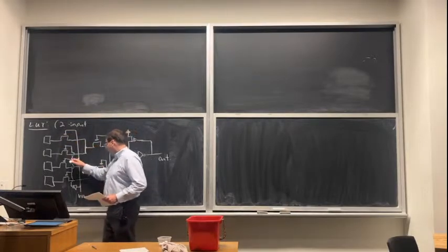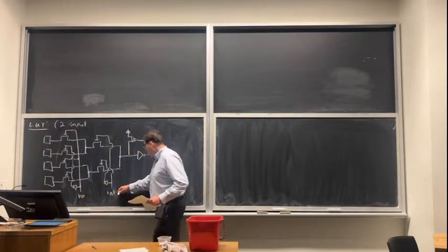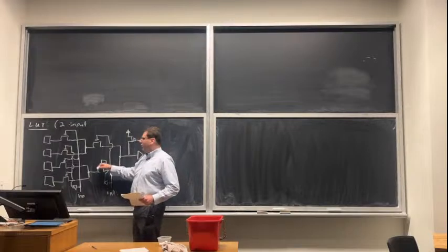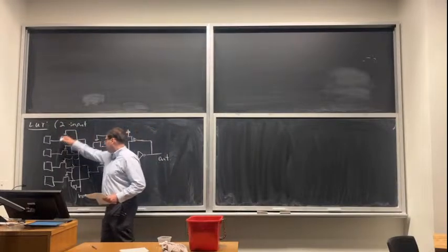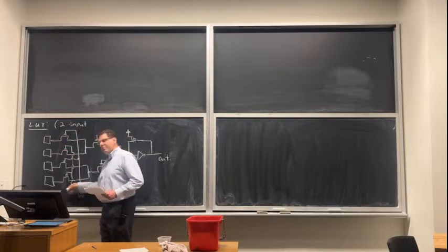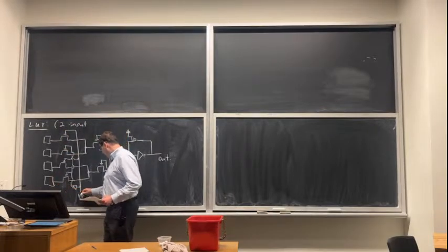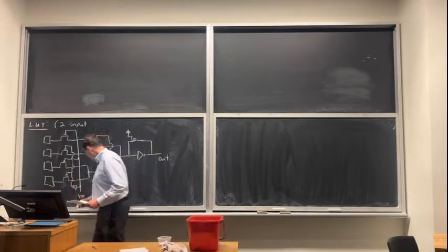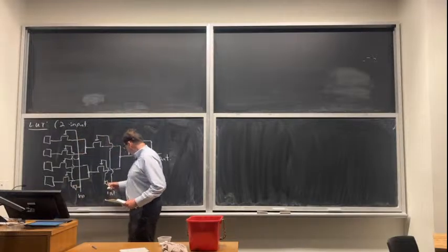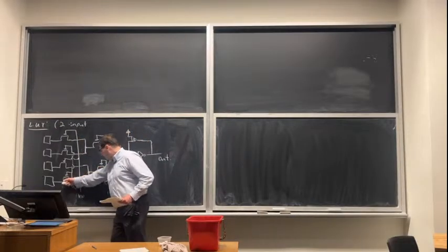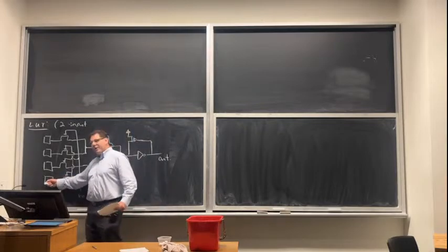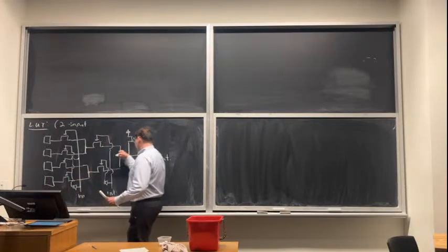And so on. Okay, so when input 1 is 0, this transistor's on, this transistor's off, so we don't care what's happening up here, we only care what's happening down here. And if input 0 was also 0, so if this was 0 and this is 0, I turn on this transistor, and whatever I stored in here makes it out to my output.